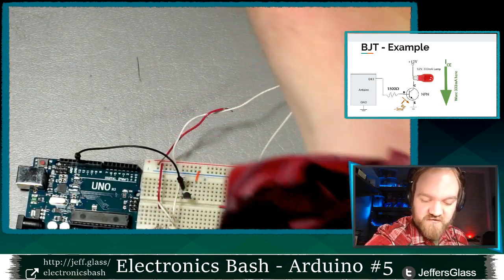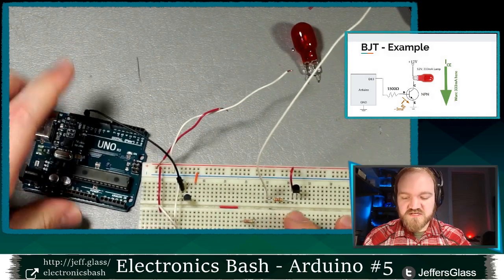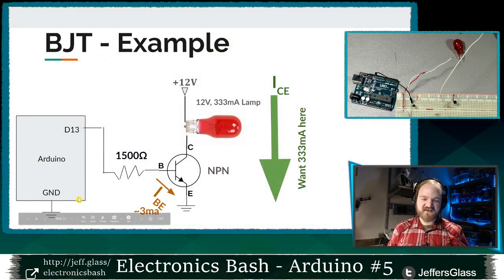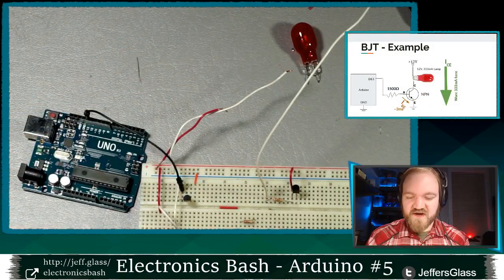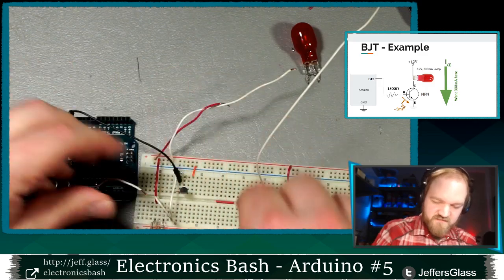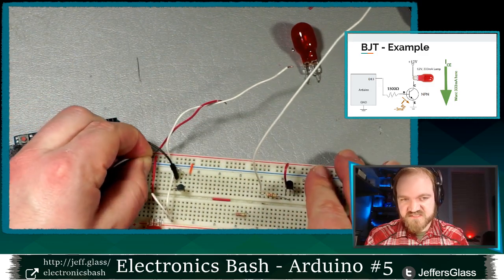And I want to make sure that I also connect one of the ground positions on my Arduino to the ground position of my circuit here. You can see I drew it into the circuit diagram here. You want to make sure that all of the parts of your circuit share this common ground, because if current is going to flow from our digital pin into our transistor, you may have heard that current always needs a return, like electricity has to have a full circuit. These are both connected to the same ground point, making sure that we have that full circuit of current flowing. So I'm going to take a bit of wire into one of the ground positions on my Uno here. There we go, and I will connect that to the ground rail just there, right?